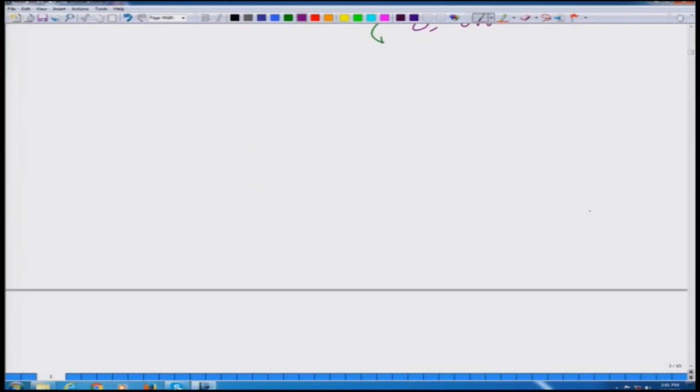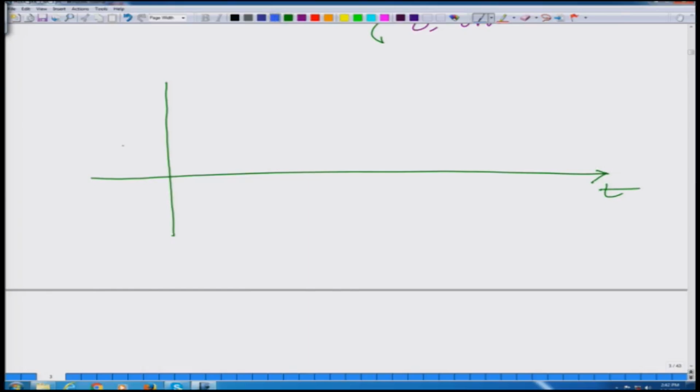Now, what we are going to do with this pulse, if I have to illustrate it in a very simple fashion, let us say this is my time axis. The first symbol is basically A naught into the pulse, so this is my first symbol of height A, because remember the first digital modulation symbol is A. So, this is A naught into P sub T of t. Take the symbol, multiply it by the pulse. Okay. Now, the second symbol is more interesting, you shift the pulse by T.